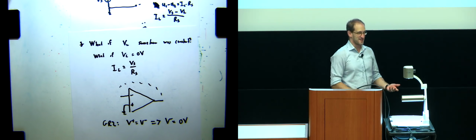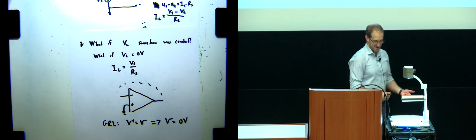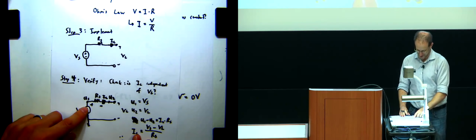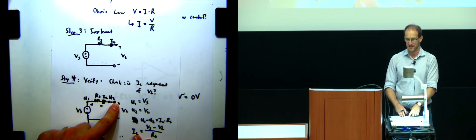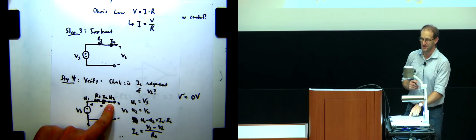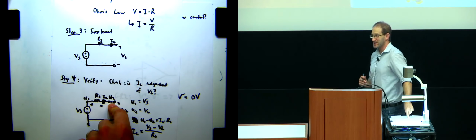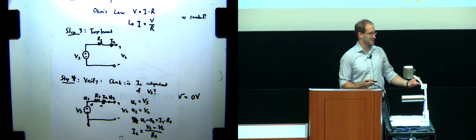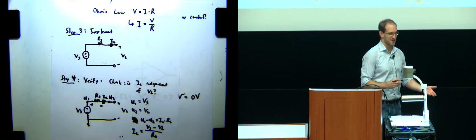So why do I bring this up? Well, that means that if somehow I can take this circuit and connect U2 to some kind of op amp in negative feedback, I can make it so that the voltage seen at this U2 indeed will be 0 volts, right? And so now the question is, okay, but how does the rest of this really work out? How do I actually get this thing to behave as this current source?